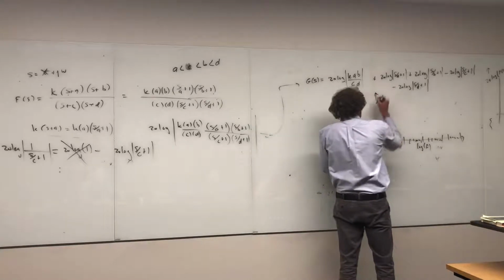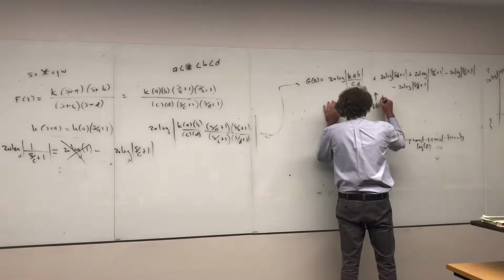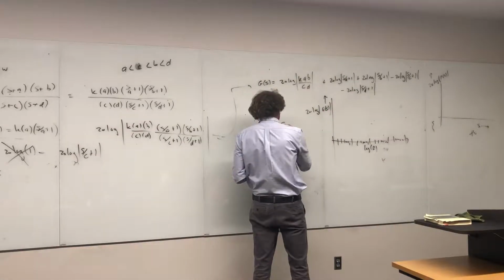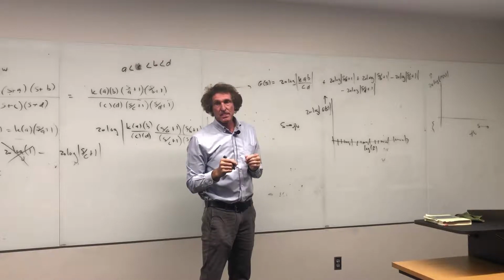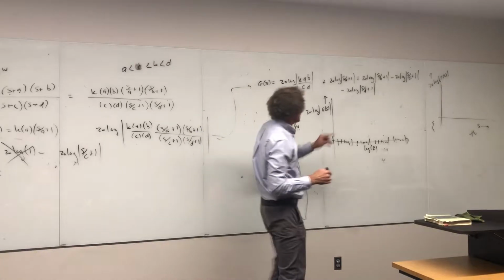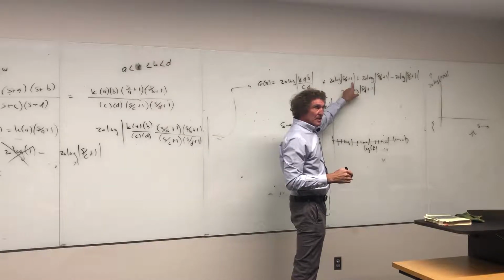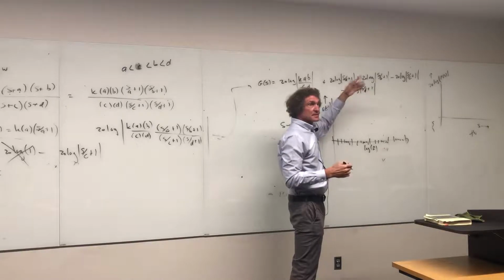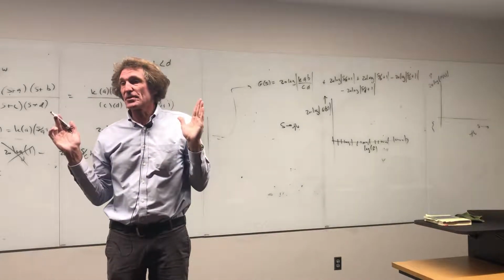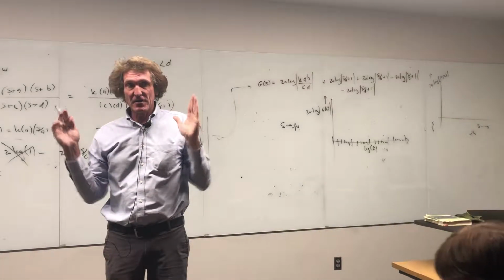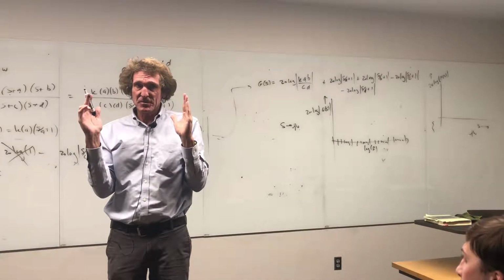Here, it's just 20 times the log of the magnitude of G of S. But now we do that thing, we let S go to J omega. And here's the real magic of this. The only thing we care about is the point where S over A becomes 1. Then it's got the same value as 1 here, and because it's a J omega, if you have J1 plus 1, the magnitude of that is square root of 2. You're always looking for square root of 2 increases in the value inside the absolute values that I've shown there. Does everybody understand what I'm saying without too much detail?